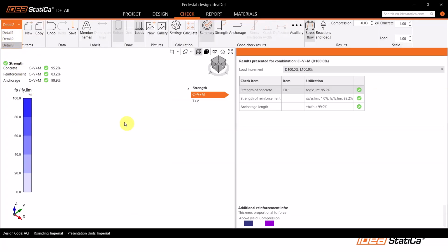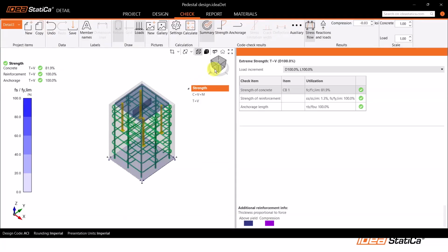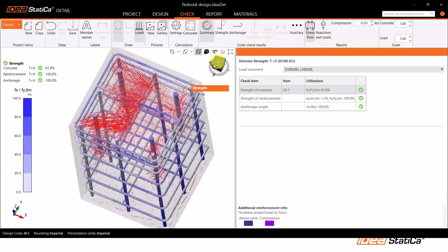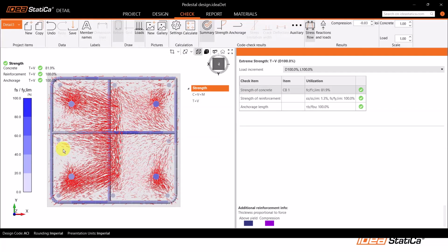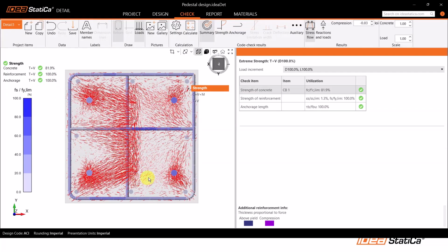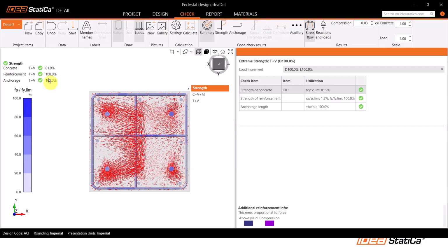And then in this detail tree, what I did is that instead of two rebars on this side, I just placed one. So I just wanted to see if that was also okay. So utilization ratios are under 100%. So, I mean, this is a very simple detail, right? Where you just have more vertical reinforcement.